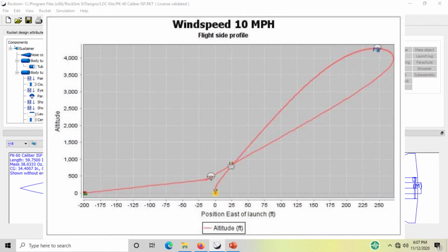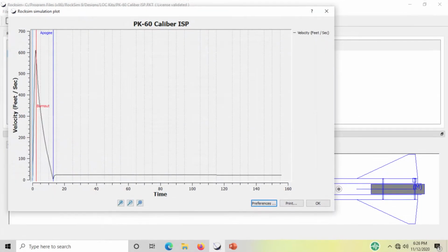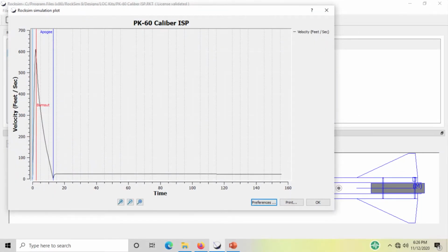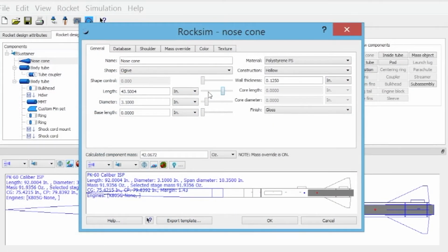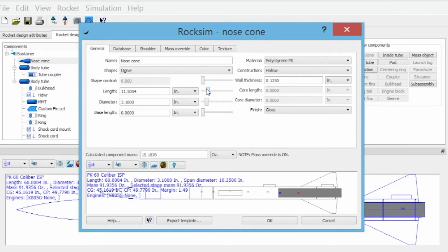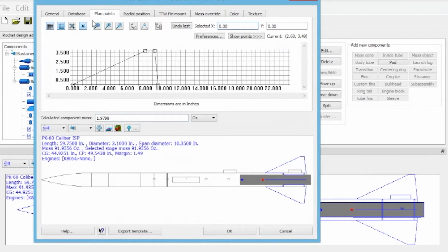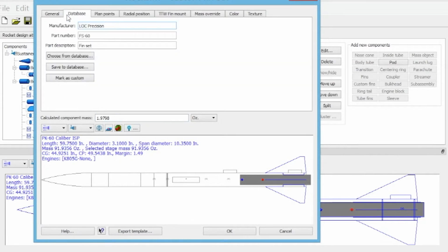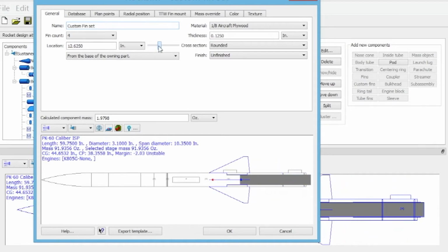The results of your simulation can be run as reports or displayed as trajectories or graphs that can be visually interpreted to ensure you satisfy all safety and design requirements. If your simulation does not satisfy requirements, then modifications to either the simulation conditions, the motor selection, or the recovery specifications should be made, and the flight simulation repeated. If the results still do not satisfy requirements, then perhaps a different model or component should be considered.